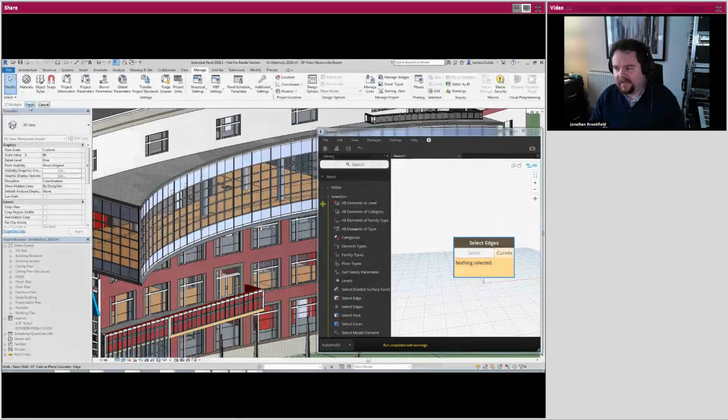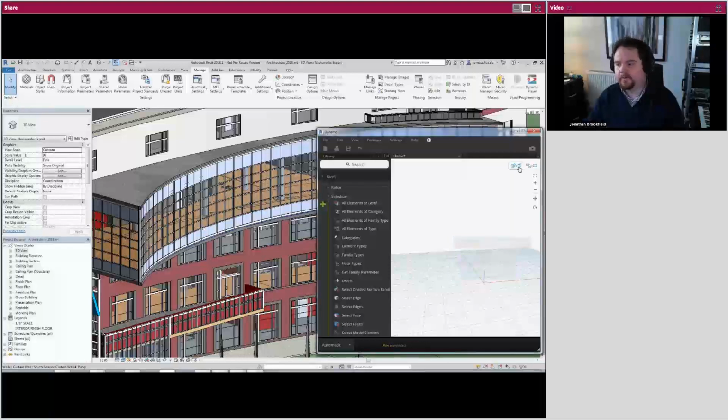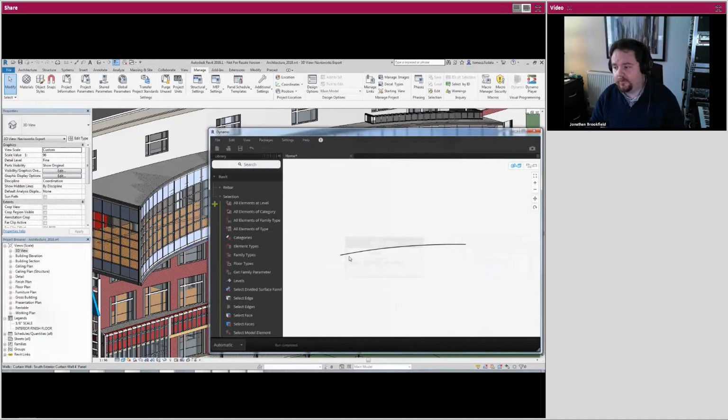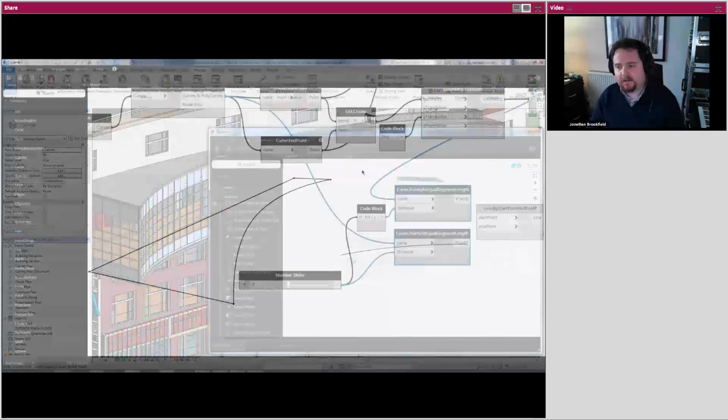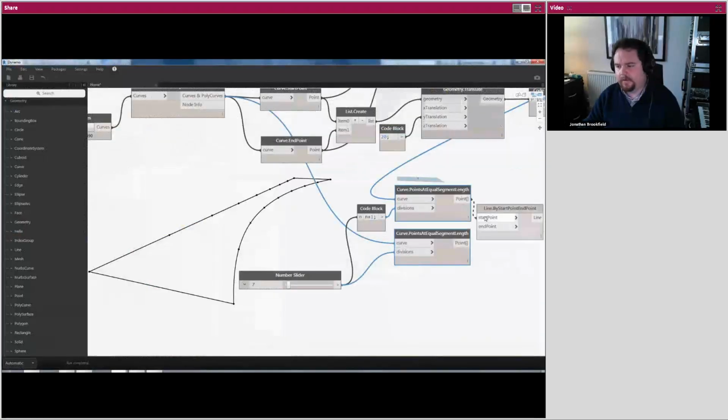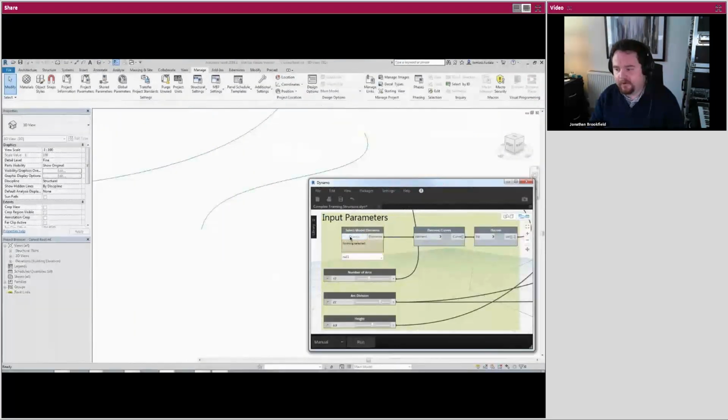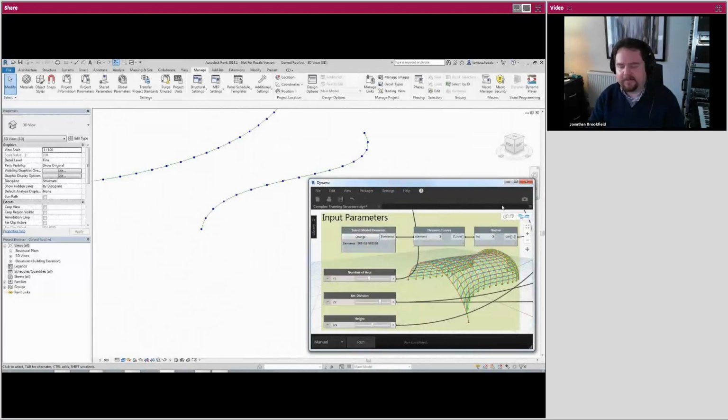Dynamo allows you to select aspects of your architectural model that you'd like to focus on and convert them to schematic structural slabs, beams, and columns. Once the selection process is complete, you can experiment with column and beam placement before finally settling on an idea that can easily be converted to a structural model that will allow you to further design detail in Revit.